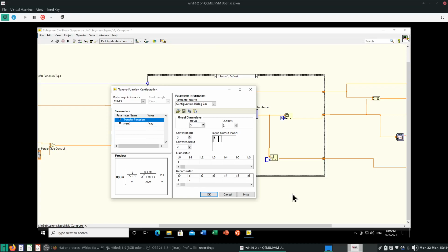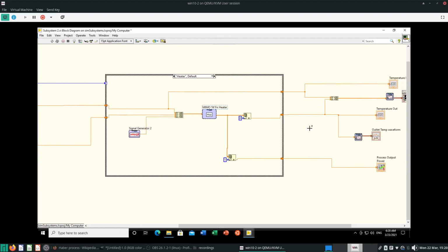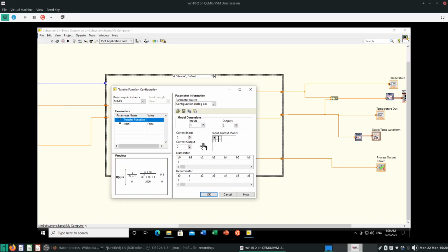Okay, so first thing, it's the inlet temperature to the outlet temperature transfer function. So it's 1 over 2s plus 1. So that gives the pattern that if your inlet temperature is at 30 degrees and then you suddenly change it to 40 degrees, if the heater power is 0, the output temperature will also be 40 degrees, which should make sense. So there's a unity gain, a gain of 1, and then some process time. Okay, so that's how I connect input temperature and output temperature. Again, it should make some intuitive physical sense, but it's not based on any thorough equation. So again, the inlet and outlet temperature are controlled by a unity gain transfer function.